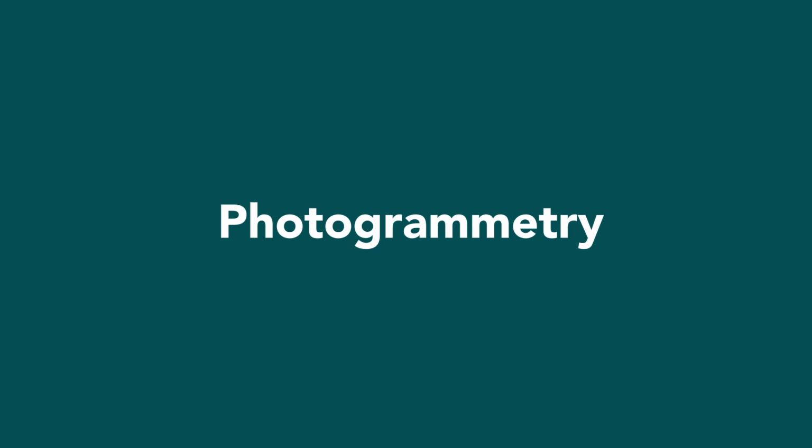Photogrammetry. So photogrammetry is the term given to the science of being able to measure and reconstruct from images. So it's essentially the term that we use to be able to describe creating these maps and models. It's the technique that is used to create 2D maps, 3D models using drone images. So anytime you see drone photogrammetry, you should mentally replace that with 2D maps and 3D models, because that's where generally it's used in the drone world.